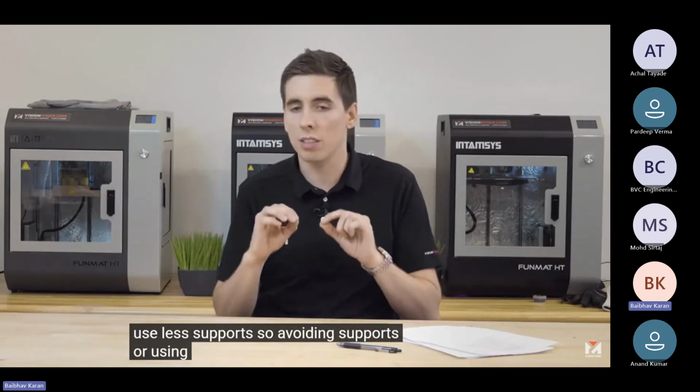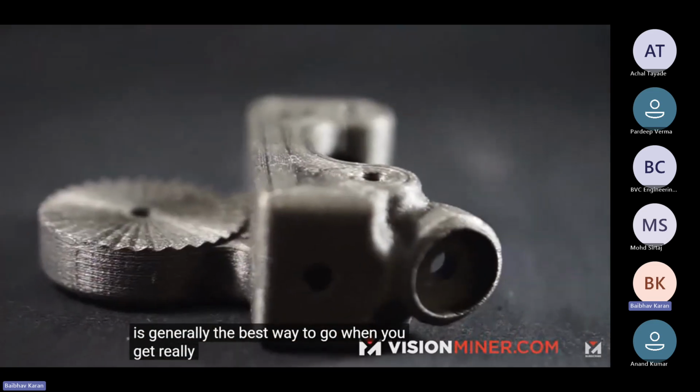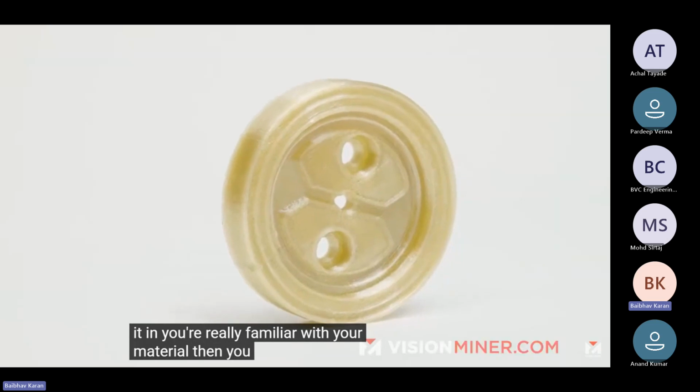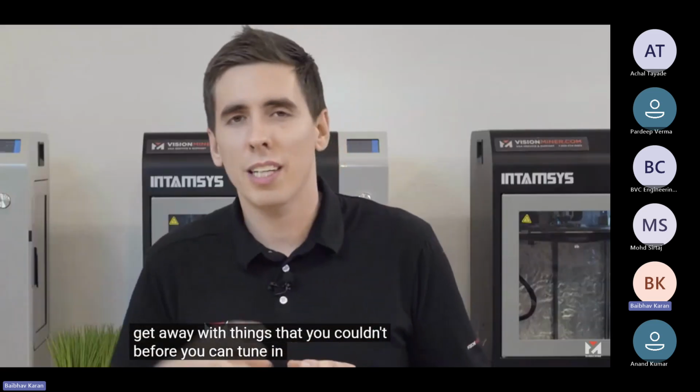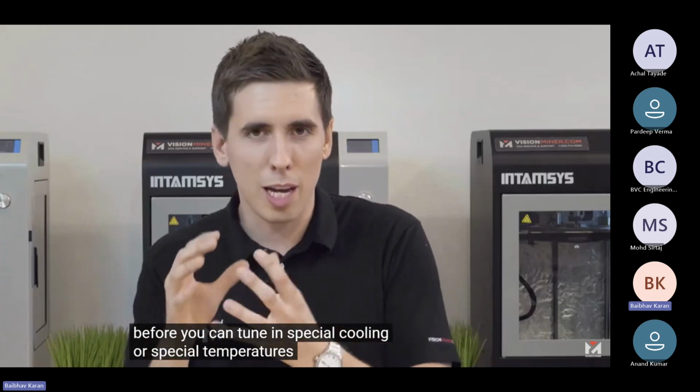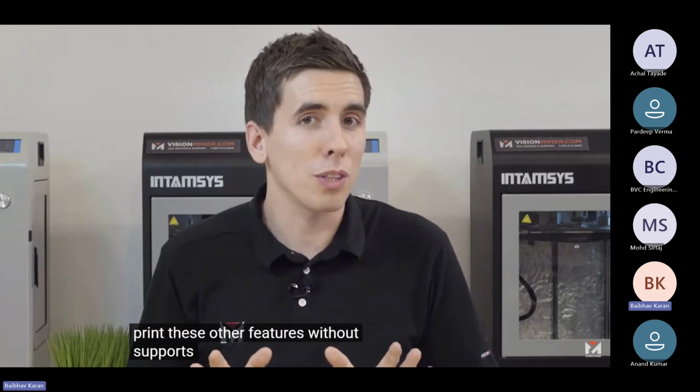So avoiding supports or using as little supports as possible is generally the best way to go. When you get really good at it and you've tuned it in and you're really familiar with your material, then you can actually sometimes get away with things that you couldn't before. You can tune in special cooling or special temperatures to allow it to print these other features without supports.